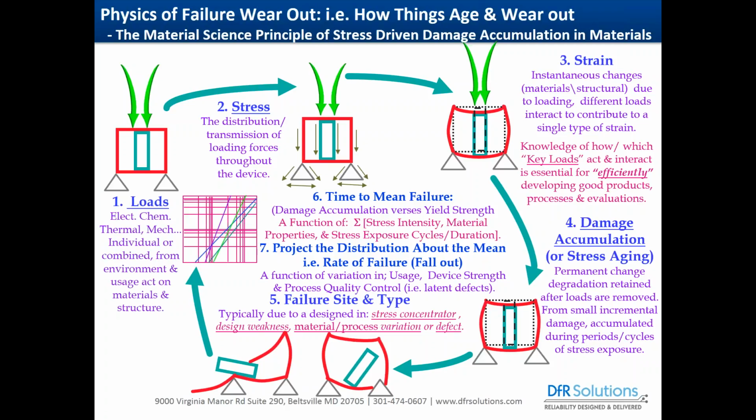Now, this is a significant advancement over where reliability prediction has typically been, where we have been limited to calculating the mean life. But the mean life means 50% of our products have already failed and 50% are still working. What we endeavor to do here is define the all-important time to first failure in order to ensure that we can design our products so that the environmental and usage conditions they are going to be exposed to make none of the parts fail, or as few of them as possible.